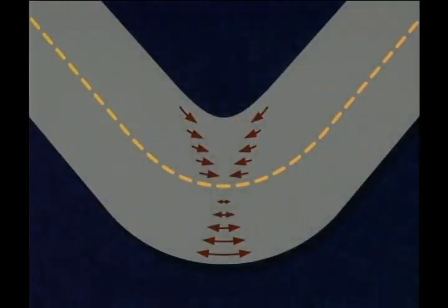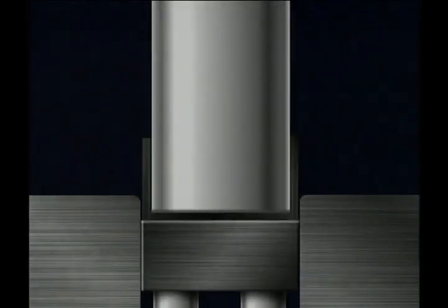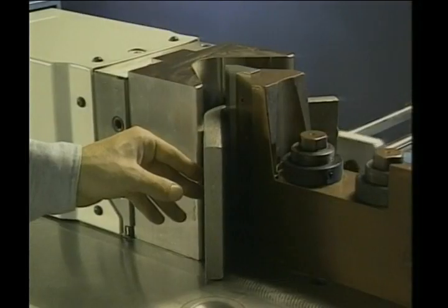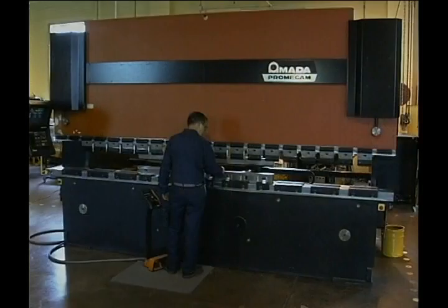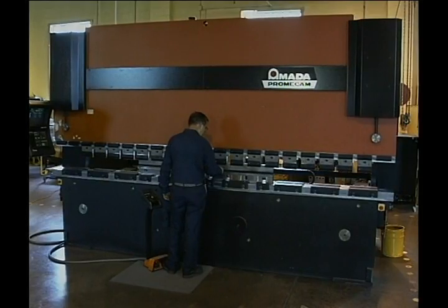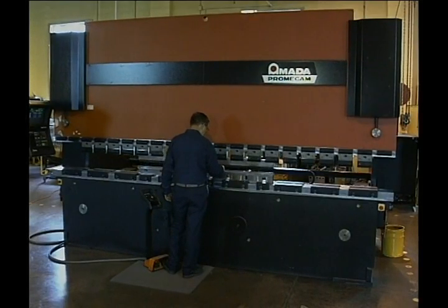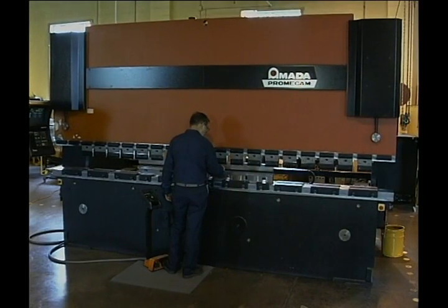The extent to which a material deforms, whether in compression or tension, is proportional to the material's perpendicular distance from the neutral axis. Bending can be performed in dies in stamping presses and on various other types of equipment. The most common of these bending machines is the press brake, chiefly because of its versatility and ease of operation. Press brakes can be used for both prototype and short-run custom work, as well as for lengthy production runs.